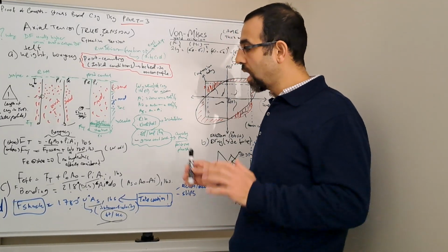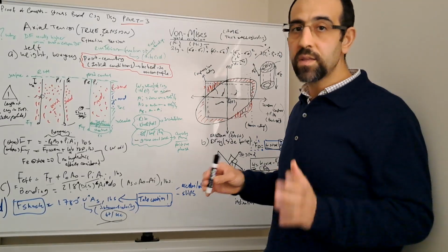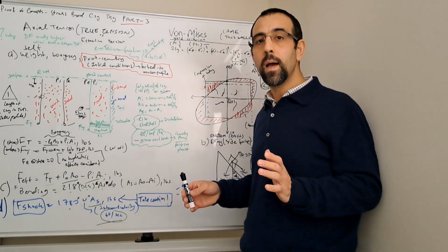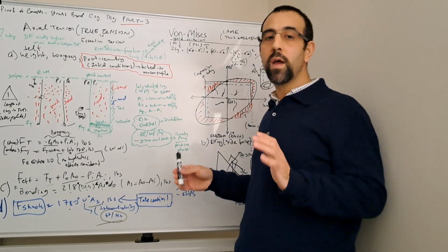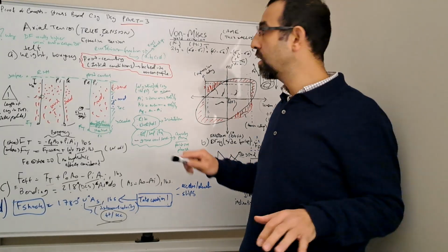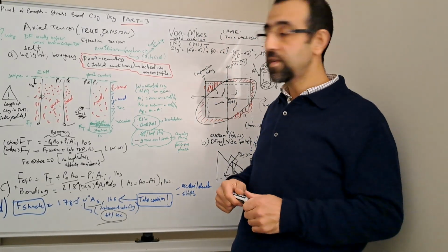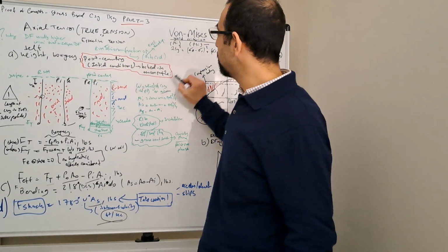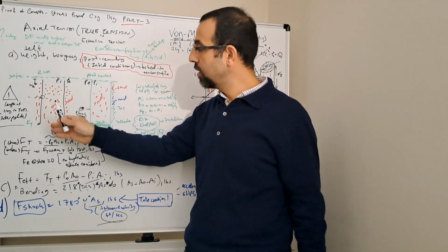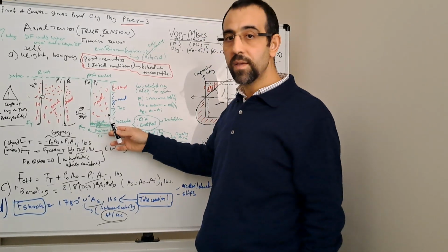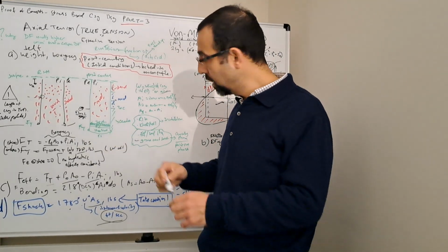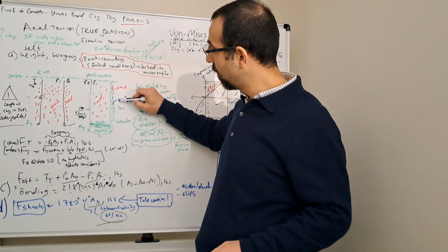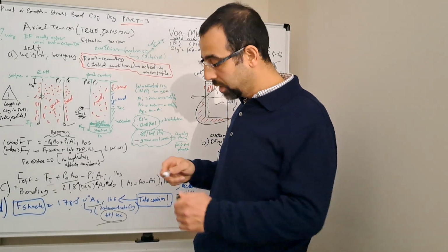However, because now the cement is not in the green state, you will have some ballooning forces acting on it, which I'm going to speak on on the second page. So let's look at this case because it's very important. We run in all the casing and we cement the casing. There's top of cement over here, you have the spacer, and then you have the mud over here.